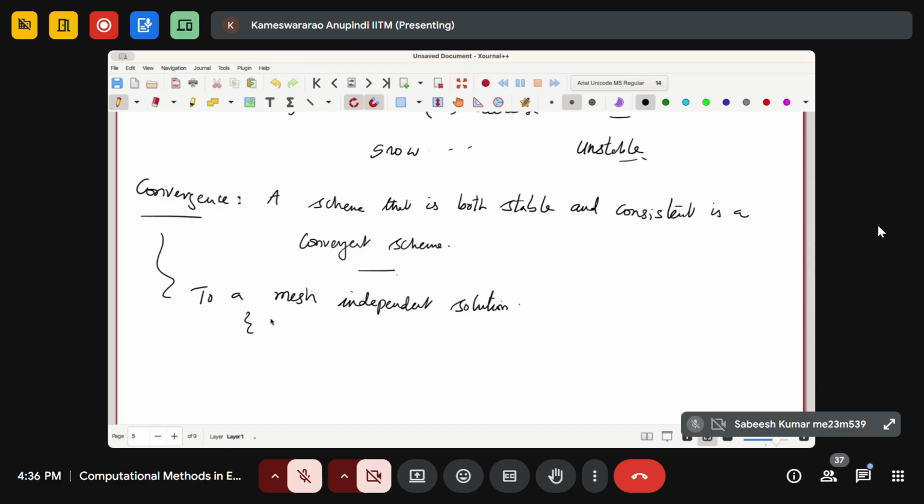So you have to rely on some kind of mesh. You find the temperature distribution over the entire brake, let us say using r, theta, phi, on a domain of maybe 15 million cells, 50 million cells. Then you would run the same problem again using maybe 80 million cells, a much higher number.